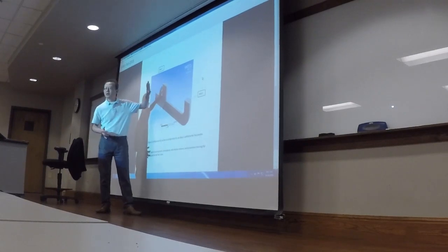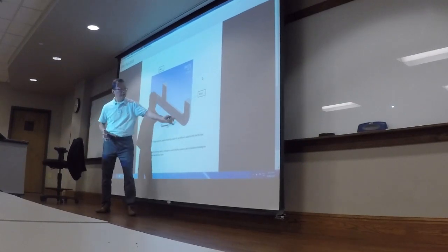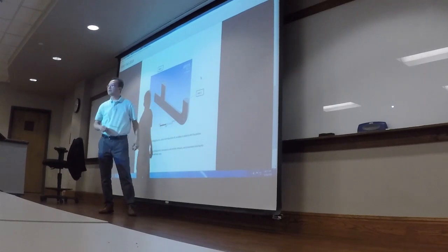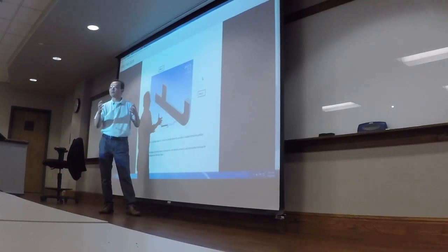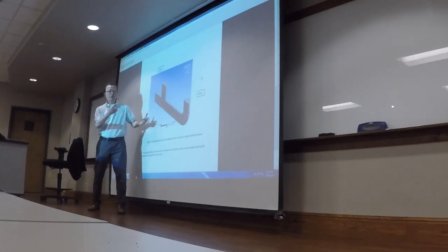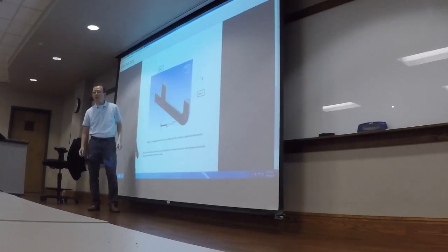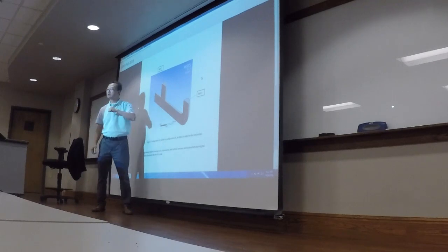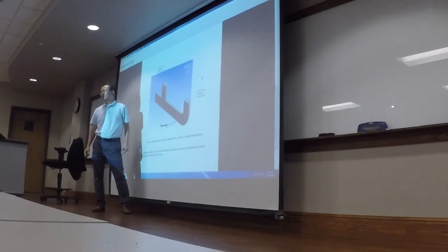The branch portion, no difference. The line portion, turn the flow 90 degrees, which means let's add more resistance to the flow. All right? So we can imagine, even before we solve the problem, compared to configuration number 1, the line portion flow should be reduced. The branch portion should be increased. By how much, we'll see.